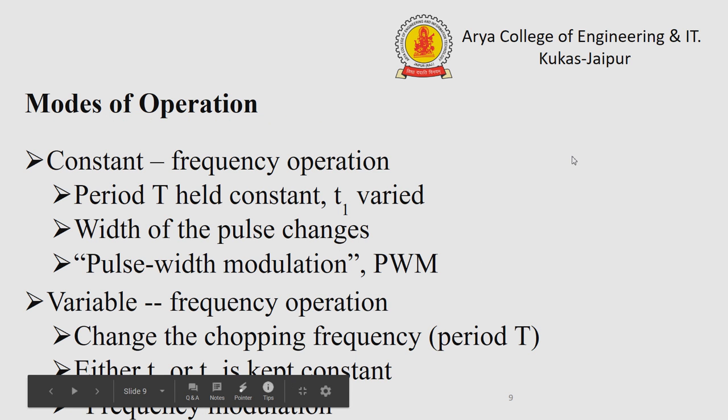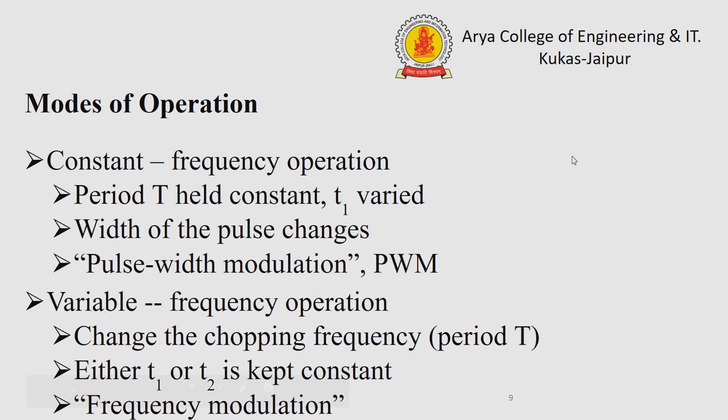Now the modes of operation: constant frequency operation, period time T held constant, T1 varied, width of pulse changes, pulse width modulation. Variable frequency operation, change the chopping frequency for time period T, neither T1 or T2 is kept constant, and last one is the frequency modulation.